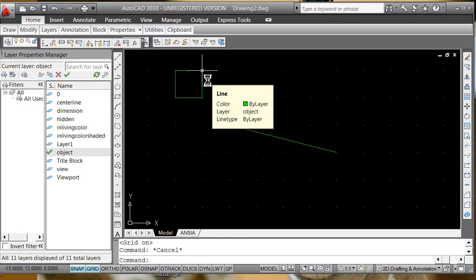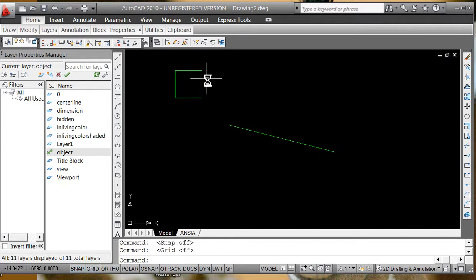If you do get off the grid, you get back on it by dealing with the F7 and the F9 together. F7, F9, again, that's called a chord. You do them both at the same time. Every now and then you'll get off. No different than the chord of the shift right click to get your object snaps, which are endpoints, midpoints, quadrants, centers, tangents.